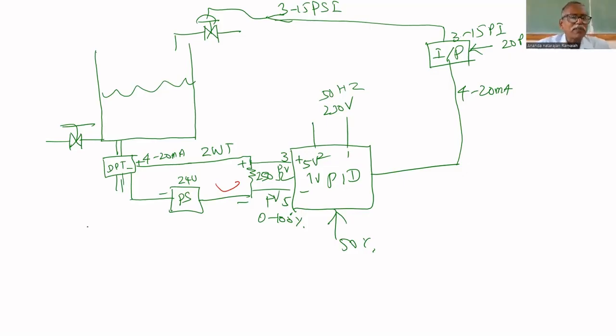Always you want to control at 50% or 35% or 30%. Depending on wherever you are asked to control, there you have to maintain the level. Let us assume that I always want to control at 50%. First bring the process to 50%. Suppose you want to drive the car at 60 kilometers per hour, first thing you will do is bring the car to 60 kilometers per hour. Then only you can maintain. Maintenance only the controller will do. The controller cannot bring it to 50%. We have to bring it to 50%. The controller will maintain at 50%. So now you bring the process to 50%.